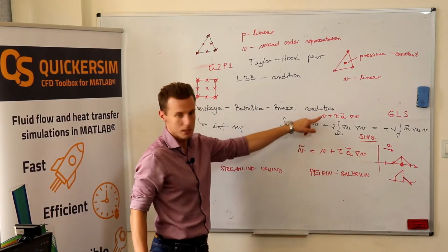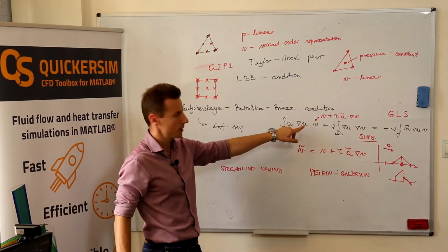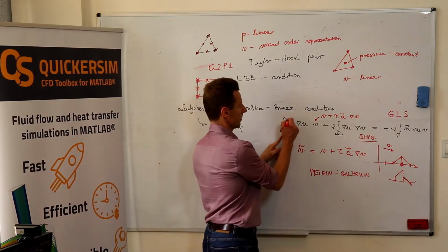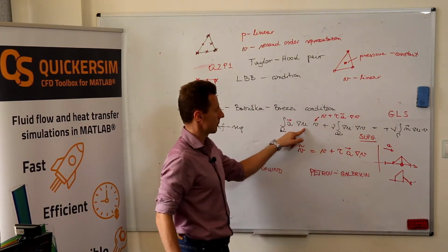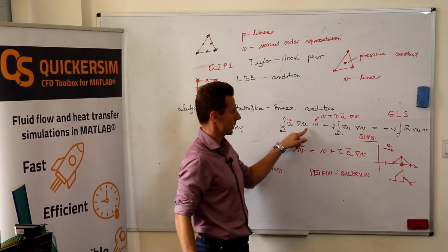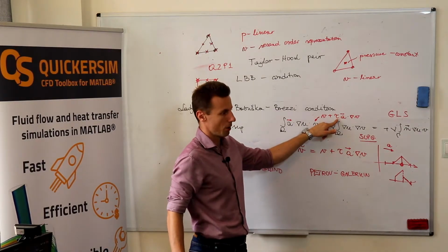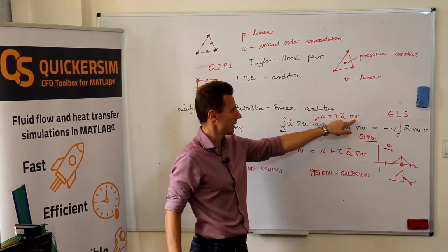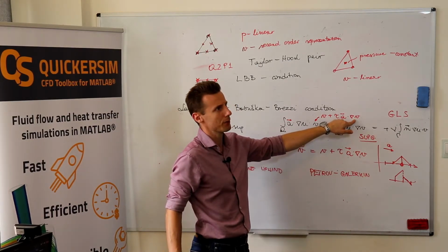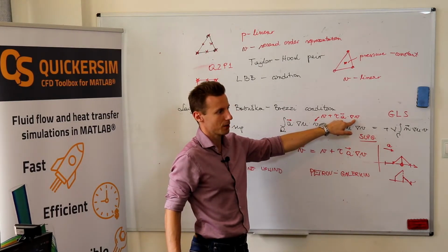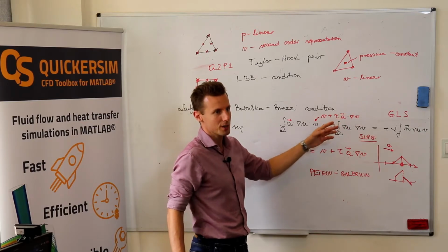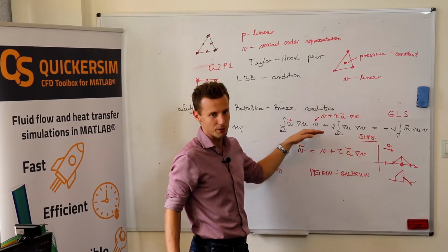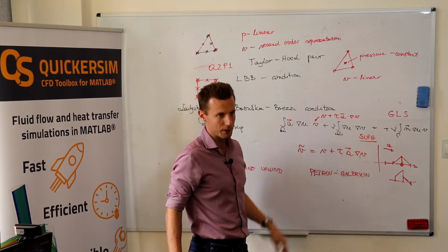The first one is the original one. But additionally, you've got the advection velocity times the gradient of U times some coefficient times velocity times gradient of V. Especially for higher order elements, it's not a constant value, so it adds to the degree of the function that needs to be integrated.